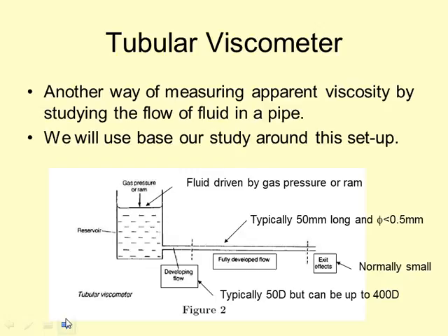Basically, this is similar to the energy equation, except we drop all the terms. We just have the pressure and the losses. Because there's nothing else. Height the same, velocity same, in and out, everything same. Fully developed for the pipe. So normally all that is left is the head loss. Head loss is equal to delta P on rho g is equal to something. So normally that's where we start.